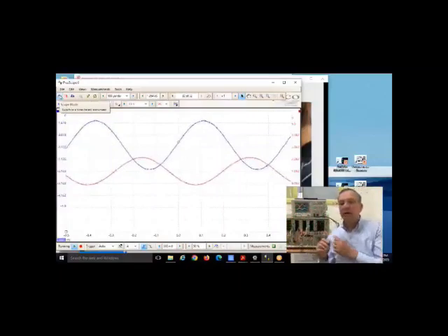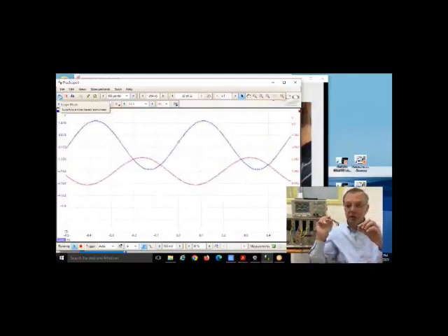But when they implement them on TIMS, they'll actually see real live signals, and they'll see that the signals using real electronics are not 100% mathematically perfect. There are little offsets. So you'll see other quadrature components and so on, and I can demonstrate that. So the signal will never be 100% null. There will always be a small component because of the nonlinearities, because of the phase and frequency effects of real electronics.